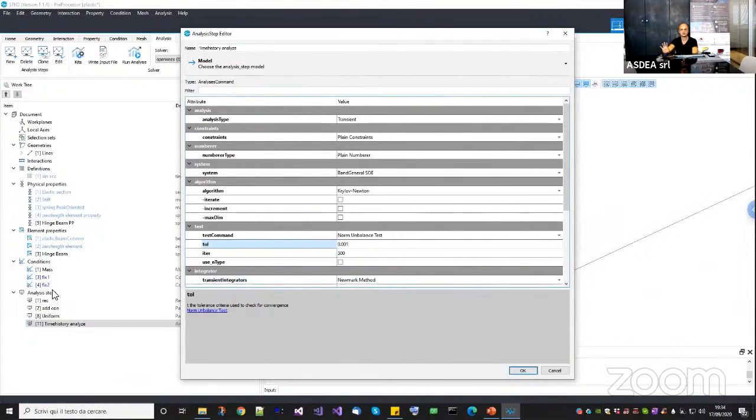So first of all, keep in mind what the units are. Keep in mind if you're using only displacement and forces or also rotations and moments, because they have different units. That's the main problem. When you check the unbalance or the displacement vector, one case is having only displacement and forces, so you have length and force as units.